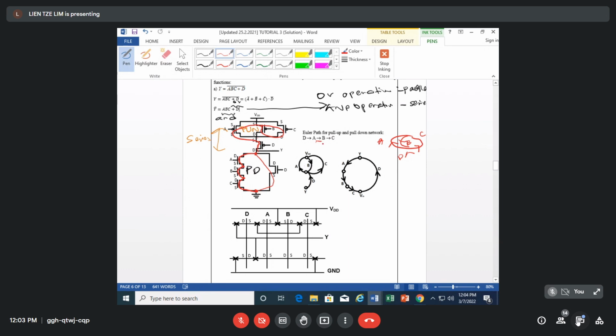The Euler path that you identify must be the same in both the pull-up and pull-down network. And the Euler path must be in one direction, so it cannot be reversed.